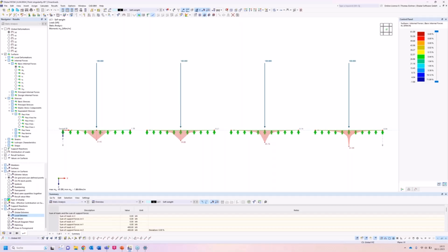For reinforced concrete, if you have a column on top or below, you would do a punching check, which treats the singularity. For this case in here, we have a nodal single load. So we could do a punching check. It's called, I think, an indirect punching check.